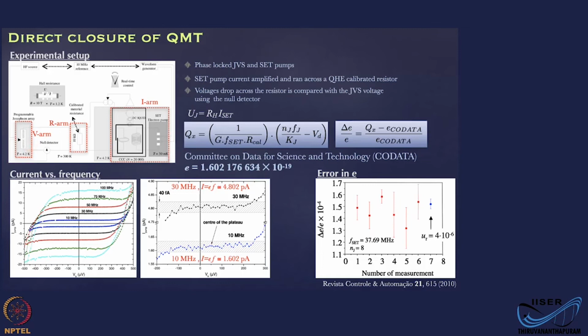So the idea here is, you have the single electron tunneling phenomenon and the current generated gets amplified by something called a cryogenic current comparator. That is basically a current amplifier with very high precision, metrology standard precision, with a very high gain of 20,000 or so. We will not go over the details of this current comparator much, but this is a current preamplifier.